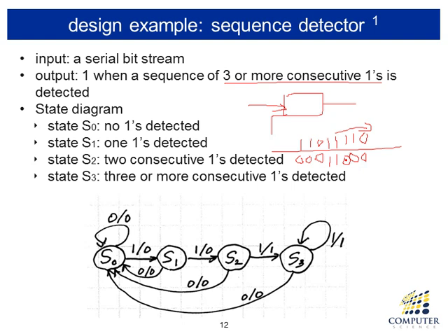For a state diagram, you need to first find the states and the meaning of each state. In doing so, you can actually simulate the system so that you can figure out how many states we need and what is the meaning of each state.